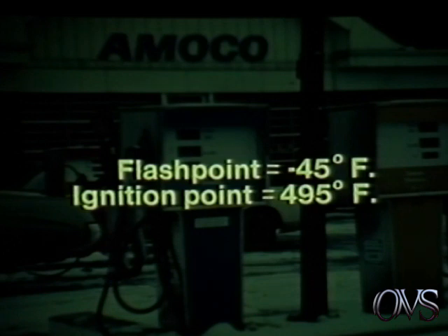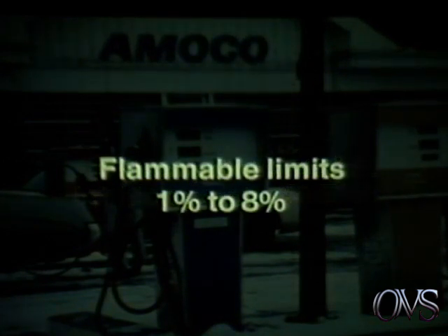Gasoline vapors are also highly flammable. The limits of flammability are between 1 and 8% gasoline vapors to air. Within this range, gasoline can flash on exposure to a spark and may flash back to the source of the vapors.